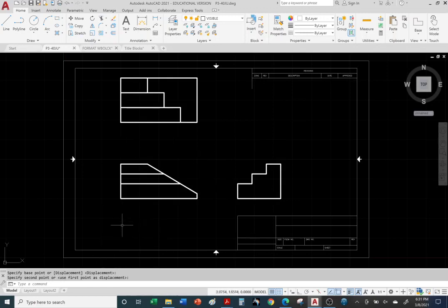So you have to put notes about how are you going to machine this? How are you going to label it with the part number? What type of material are you using? Are you going to paint this? Are you going to have some areas taped off before you paint? Okay, so you're going to put all this in your general notes.